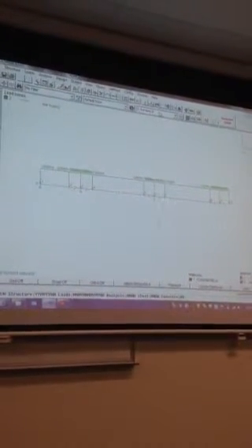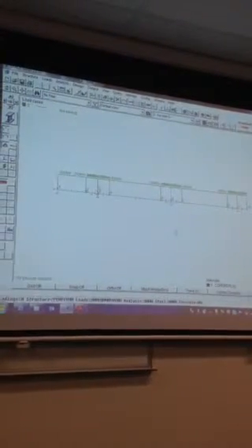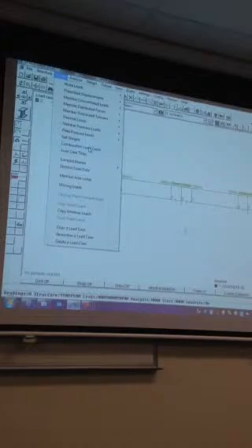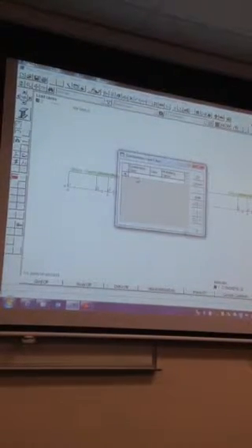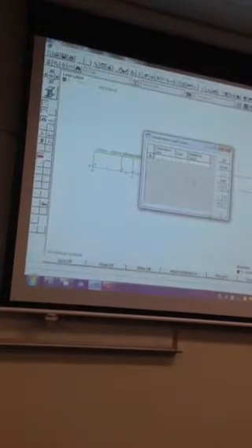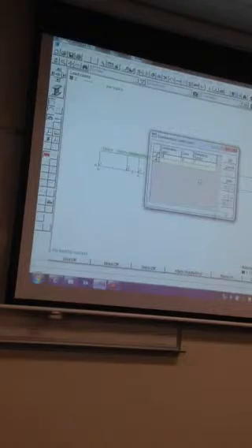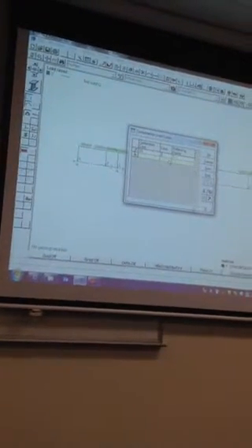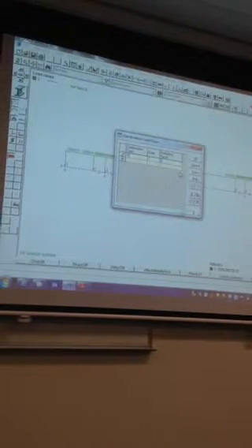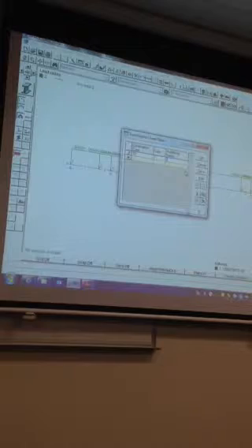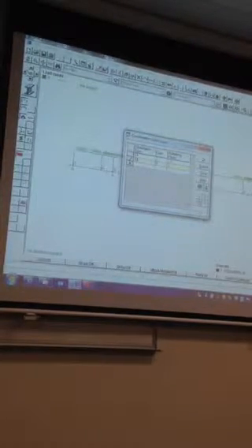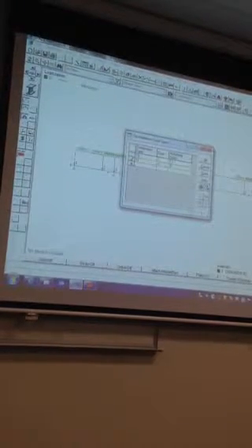So we've got all of our loads in place. We've got a geometry in place. We've got materials in place, so that's all good. So the next step we need to look at is combination load cases. So this is where we can use combinations of load case 1 and load case 2. So we'd normally start those at 10. You don't need to. So we can say load case 10 consists of load case 1, and what's our multiplying factor for the dead load? 1.2. 1.2, beautiful. We look at load case 10, we've got to add load case 2 and 1.5.